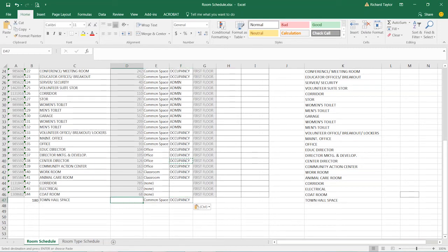Now, I can't fill out the area because it's actually going to be an unplaced room. And in fact, that's a good way, when you look at this, the items that are in gray are not editable. So for instance, I couldn't change first floor, the name of it, to second floor. Now, in a different link, if I was sending out the names of the floors, then I would be able to edit that information. But because here we're only referencing the level name of the room, and this room hasn't been placed, I'm not able to edit this information.